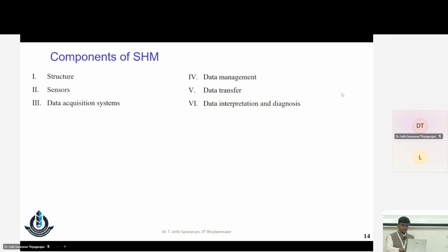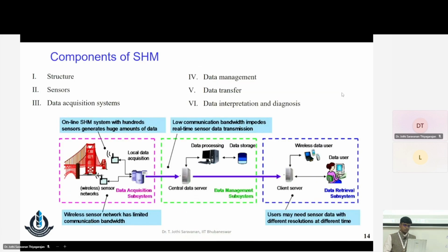Of course, components you understand, okay. This is a very simple figure where you try to understand how online health monitoring can be done, okay. Nowadays this is quite simple, where you use wireless sensors. If you have a big structural system, you have multiple sensors, so you try to communicate between the sensors. That is something called the multi-hop technique. You try to send the data from one point to another. If you imagine this is 1 kilometer, you will have multiple sensors, but you will be sitting here, which is something called the sink node, okay.